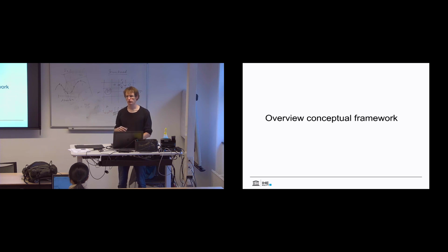So if you would be using Delft3D and you make a model of that, and you run it, and you say, well, that's not optimal, that doesn't meet the criteria that you proposed. They have to go back to the design table. They have to make a new design. They may relocate it. So you have to make your refinements in your grid somewhere else. That means that you have to redo your boundary conditions unless you take the exact same number of rows and columns.